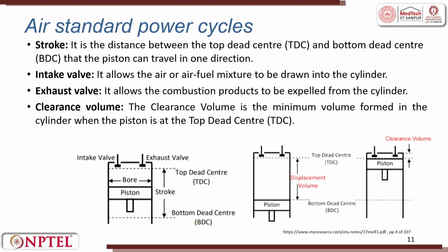Then what is the intake valve? It is the air inlet valve, and it allows the air or the air fuel mixture to be drawn into the cylinder. Air is plain air. Air fuel mixture means air plus some volatile material when it enters inside. Then the exhaust valve: after the combustion is over, it allows the combusted product to be expelled from the cylinder.